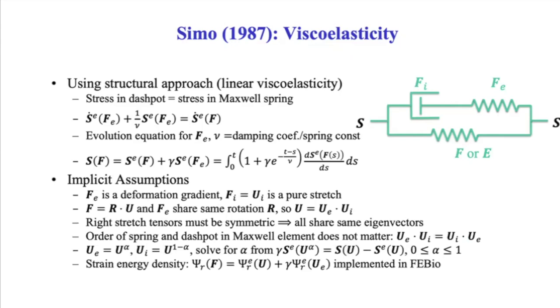And here's what we discovered. There are a number of interesting theoretical constraints. Again, if you're not in the field of finite viscoelasticity, this could be the most boring portion of the presentation. I promise there'll be more interesting and practical things later. But when you do finite deformation theory, you have to recognize that your deformation gradient here is a combination of a rotation and a stretch. So this rotation and the stretch, you can ascribe it to the total deformation gradient. You can always calculate it after you find the solution for the stretch. The question becomes, what is the rotation and the stretch in the deformation gradient of the dashpot and the spring?